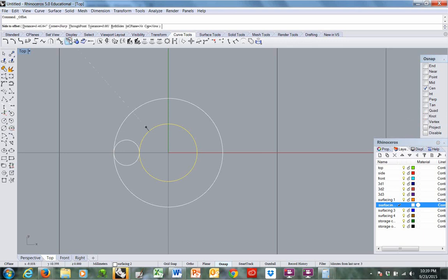Okay. Offset. Through point. Remember, if we don't do through point, it's going to go either 1, which is Rhino's default, or the last distance we used. If we hit through point, or T enter, we can rubber band, we can pick our distance. I'm going to touch the outside of this circle to activate a center snap. Remember, Rhino needs you to touch the circumference of a circle so it can calculate its center. And I have my 3 reference curves.